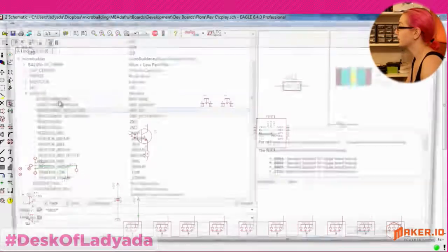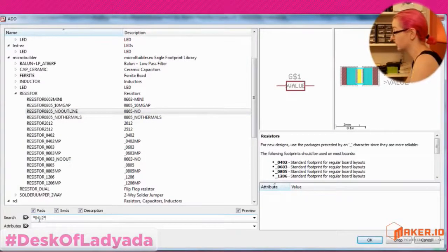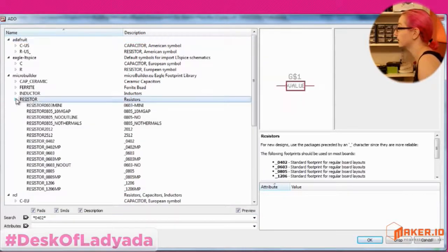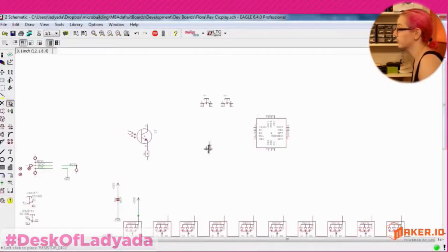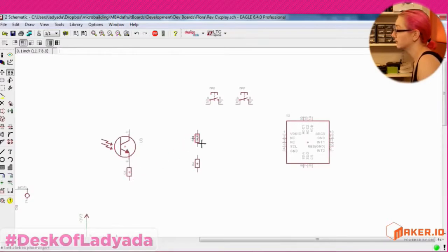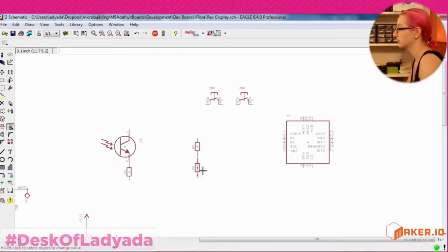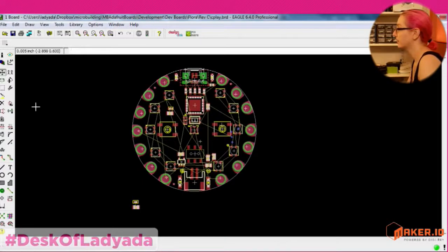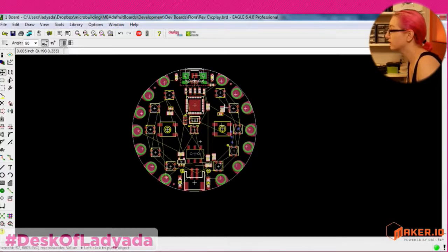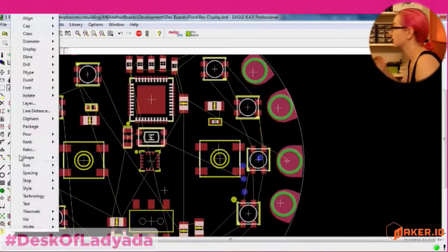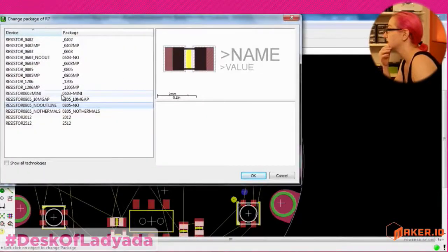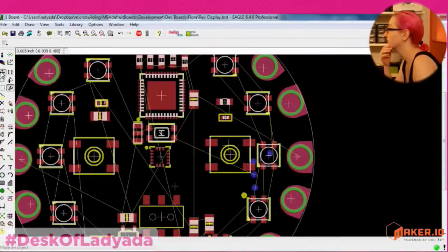Okay, next up we're going to get a thermistor. Now the thermistor is just an 0402 resistor. It's basically what it is. It's a resistor with certain thermal properties. So we'll call this 10K thermistor. And it's on the right side, so I'll put this over here. Actually, I ended up picking a 603. So this is a thermistor. Those are the easy ones.